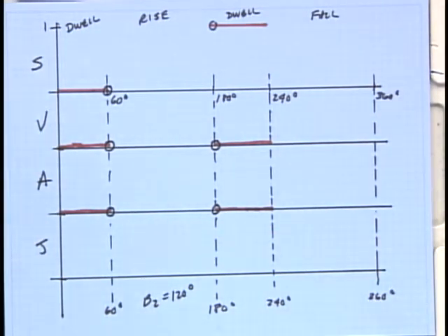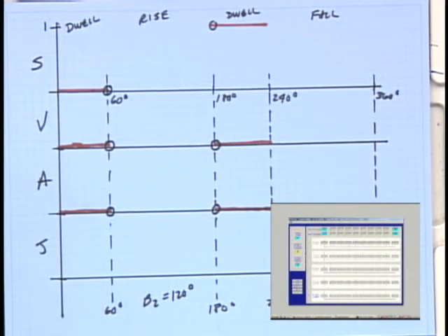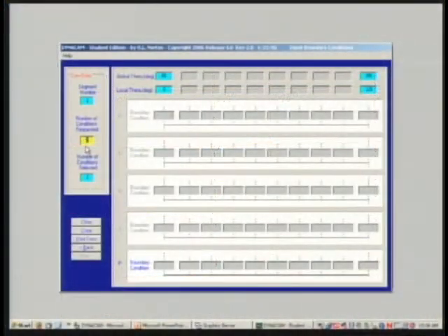Back in Dynacam, I'm going to tell it that I want 6 boundary conditions over here, and when I do that, it will wake this other part of the screen up. I will bring over the values that you put in on the previous screen, which are the first 2 boundary conditions. S is 0 at the beginning and 1 at the end of my beta. Here's my beta numbers up here. Actually, this is beta over here.